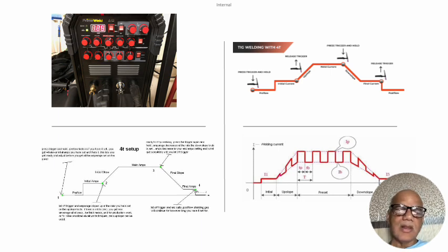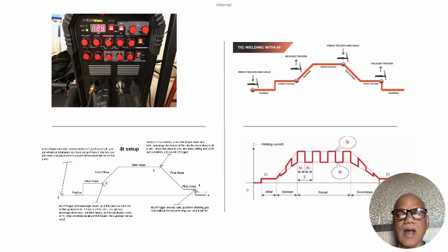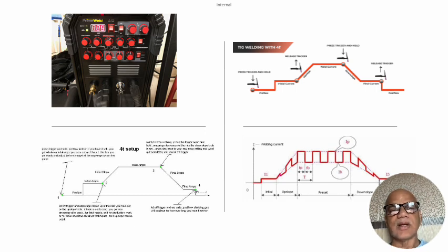So from a single adjustment of current, see how many knobs you have to adjust today to get the best welding characteristics possible. And thanks to the latest electronics and the involvement of electronic engineers in the development of welding machines, we are getting such beautiful voltage-current characteristics, plus pulsing of current to adjust.